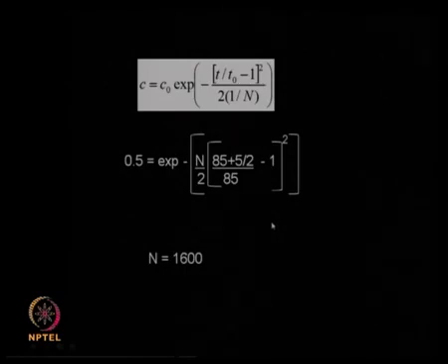So you see we did two problems, both calculating the number of theoretical stages, both based on a simple experimental procedure. You inject your solute at time equal to 0 and see when the solute is coming out or eluting out, you know the time.